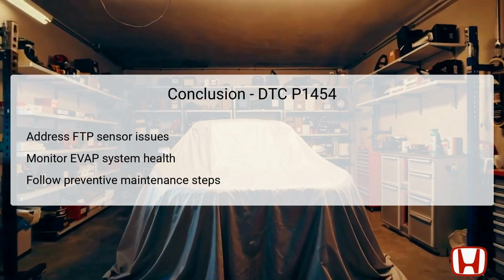In summary, addressing DTC P1454 involves a systematic approach to diagnosing and resolving issues related to the FTP sensor circuit. Understanding the sensor's role and the consequences of its failure is key to effective troubleshooting. By following the outlined steps and utilizing the HDS for diagnostics, technicians can accurately pinpoint the cause of the problem